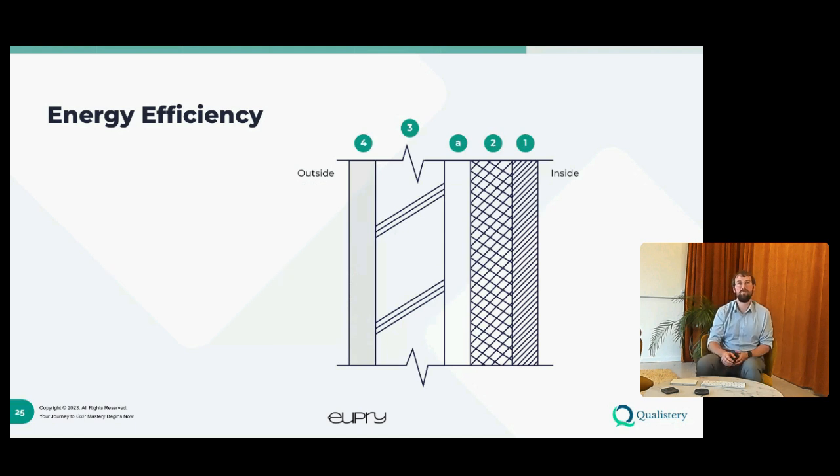Another part of this is also insulation, and this really takes a step back in terms of how warehouses are designed. One of the most prevalent cases we see is warehouses that were not built with the intention of being temperature controlled. The insulation on large surfaces, but especially roofs, tends to be insufficient, not in terms of maintaining temperature compliance per se, but in terms of not using enormous amounts of energy. And this is also a point where energy efficiency and compliance go hand in hand,